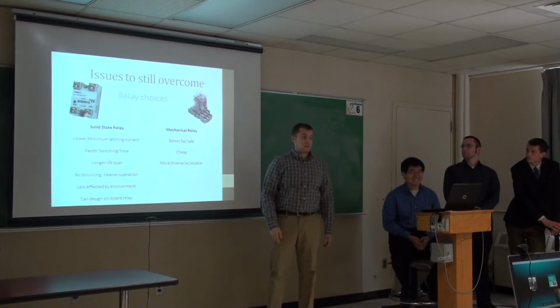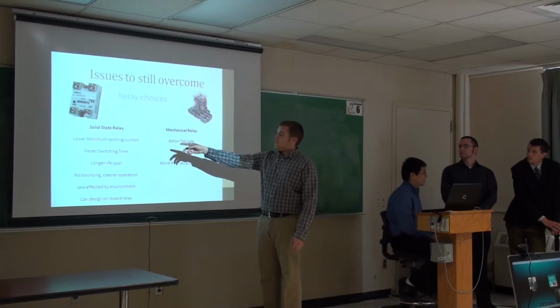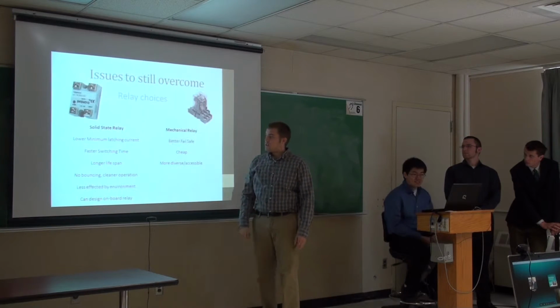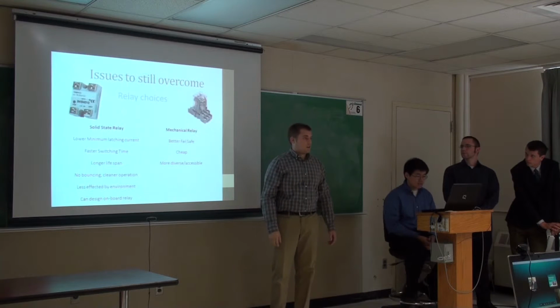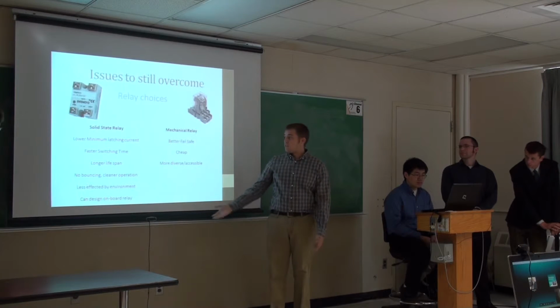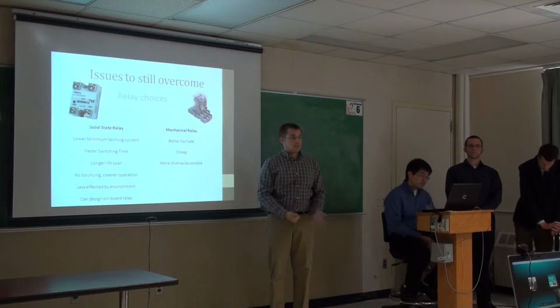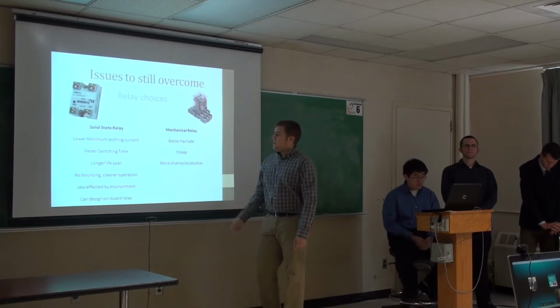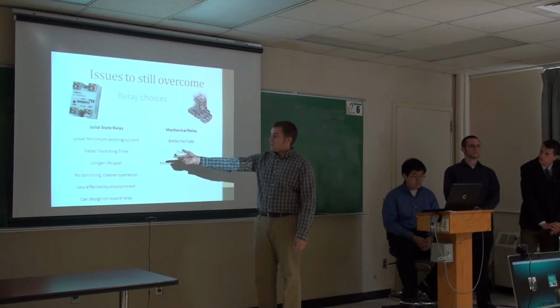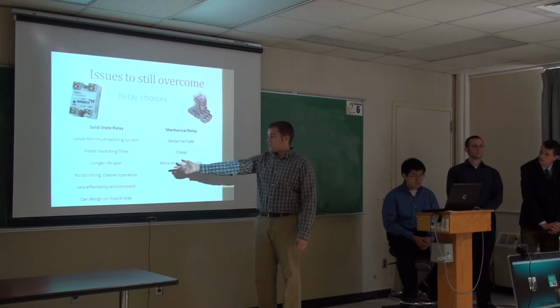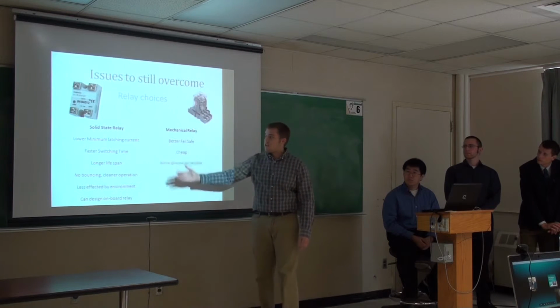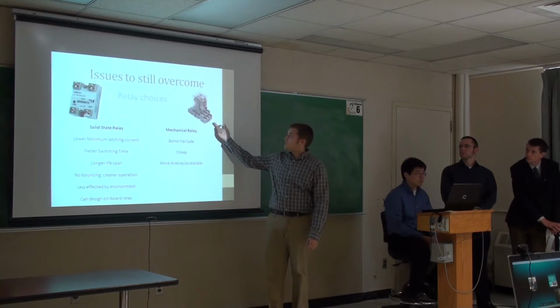A few advantages of the solid state relay is that it has a low minimum latching current, which is a benefit of ours because our microprocessor doesn't output very much current. So it's important that it has a very low latching current so we can actually change the state from open to close. It's a very fast switching time and a longer lifespan, and it doesn't bounce. It's a very clean operation. That's all because there's actually no moving parts compared to the mechanical relay.